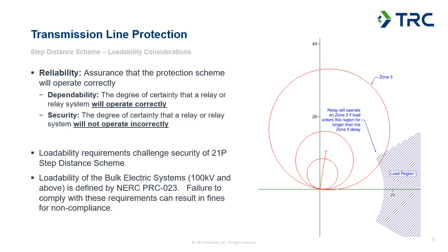They respond to zero sequence quantities, which are really only present when there's a significant unbalance. And generally, loading on the transmission system is going to be fairly balanced. So you're not going to have that zero sequence component that you would need to operate the ground distance elements.